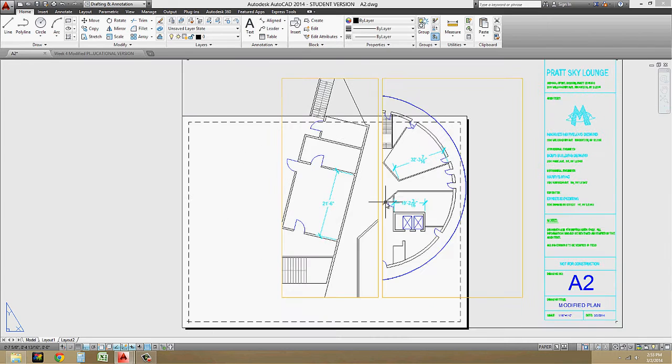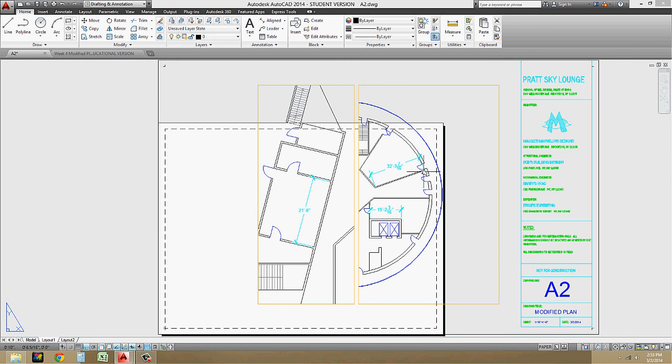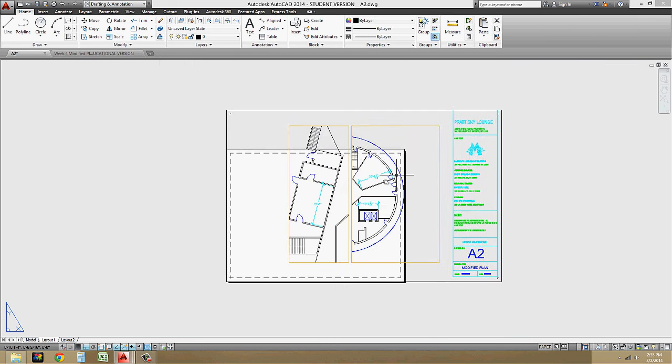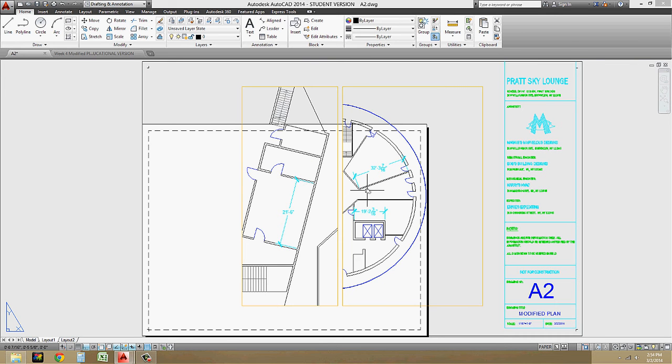Graphically on the sheet, you don't want text sizes, notes and dimensions jumping in scale. You want one scale and a uniform look throughout. So that's what it does, and it sets up to show up in some viewports and not in others.